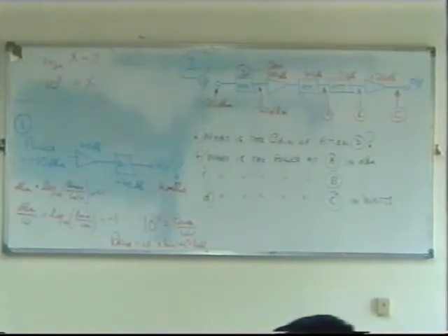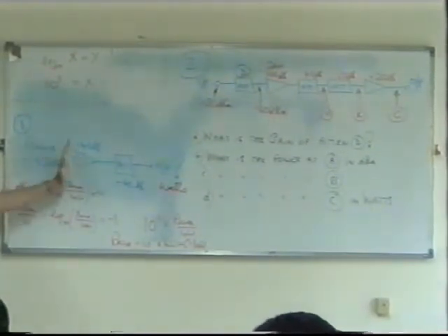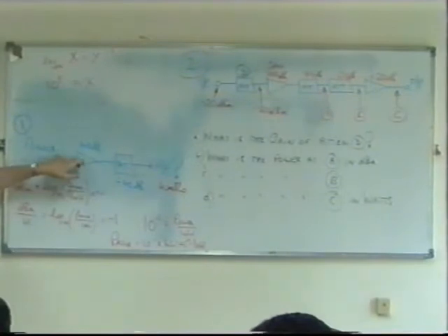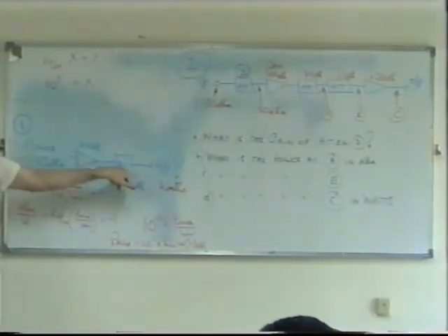Now we start with minus 10 dBm. Then we go through an amplifier, and the amplifier has a gain of 40 dBs. Then we go through an attenuator with a gain of minus 40 dBs. Well, if you already have your power in dBm, then if this was a power ratio, we would have to multiply the gain by the input, and if this was a power ratio, we would have to divide it.